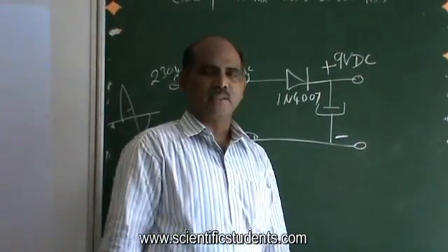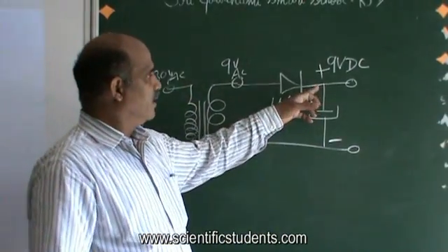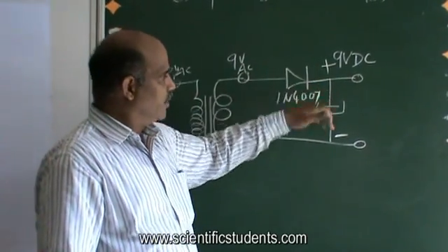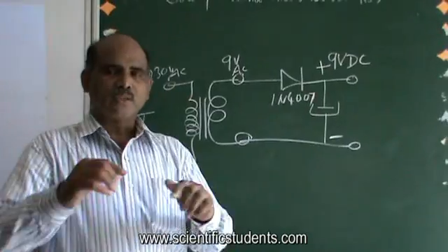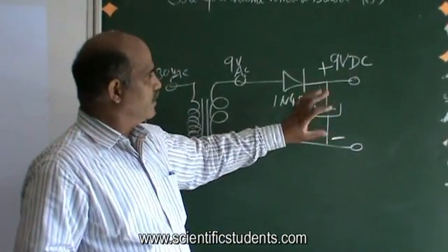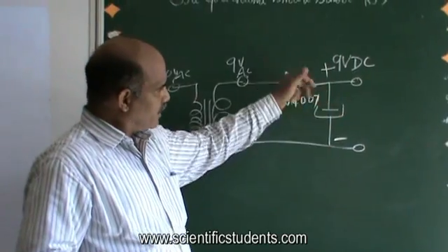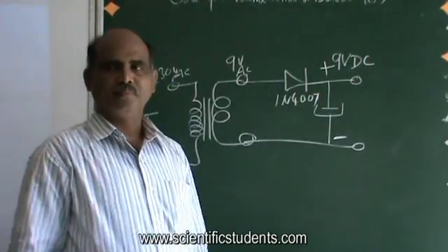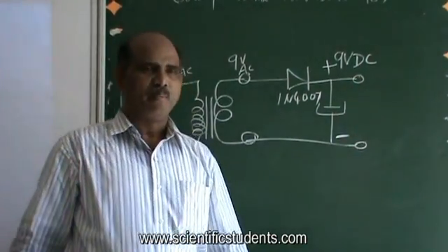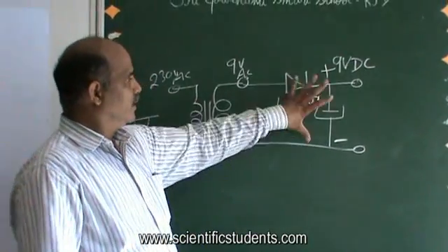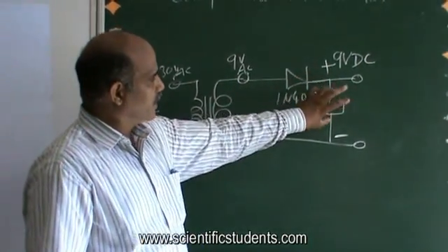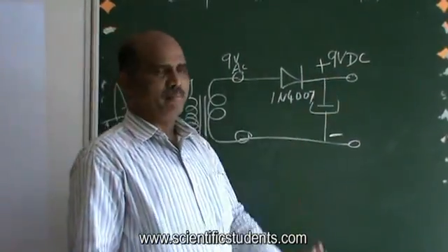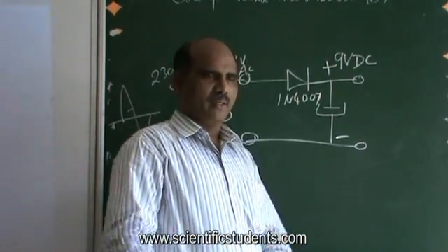So this filter capacitor will filter the leaky AC currents which are coming here or grounded here, because this capacitor is acting short circuit for AC currents. That means whatever AC component is present here after the diode also is getting grounded. So the output is a little more pure, comparatively better than without the capacitor.